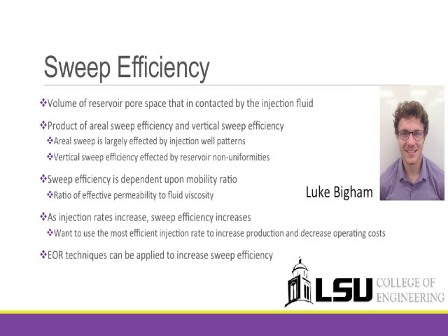Oil mobility ratios are not, and so those are the ones that typically need to be increased. Although not always the most cost-effective, an increase in injection flow rates will increase sweep efficiency. Our purpose would be to find the flow rate that gives us the best production at the lowest operating costs while still maintaining safe and feasible rates.